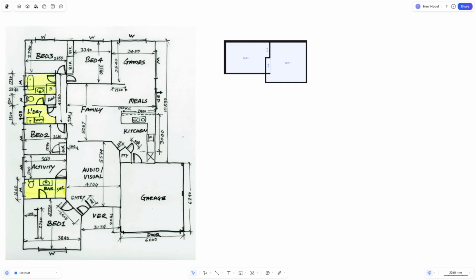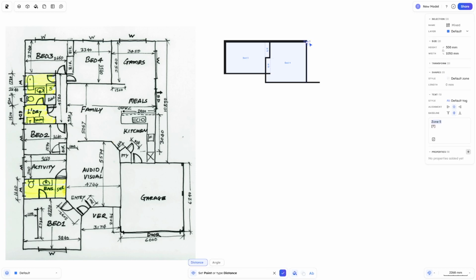room. So this is where it gets a little bit different because it's an open plan floor. So the easiest way we do this, and I'm going to suggest, is if we just drag this out here. So this is at 1200 exactly. We've got this measurement here already. We can then extend this wall. And in fact, the easiest way to do this is to draw the zone in.